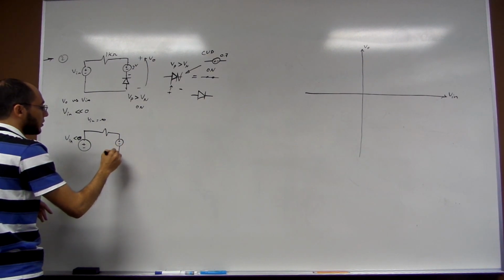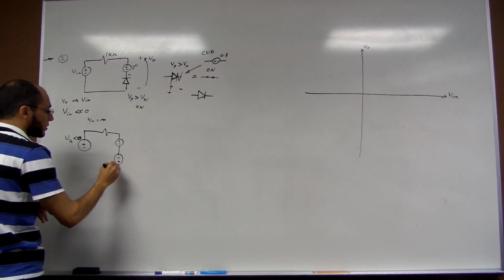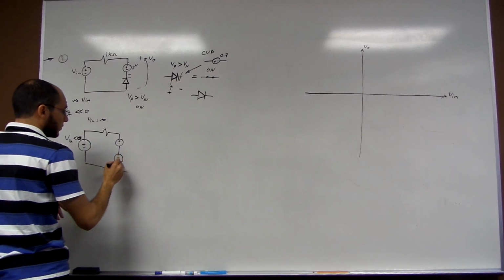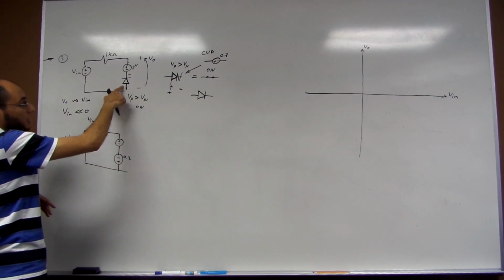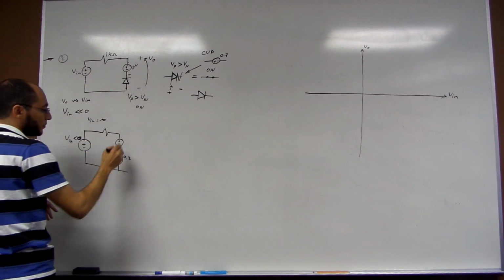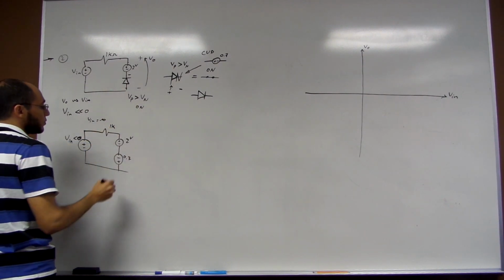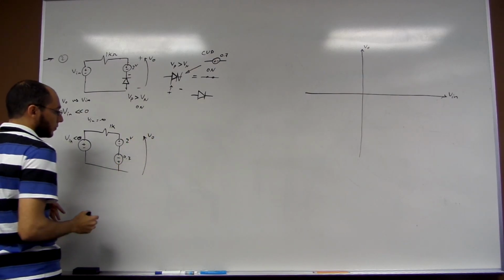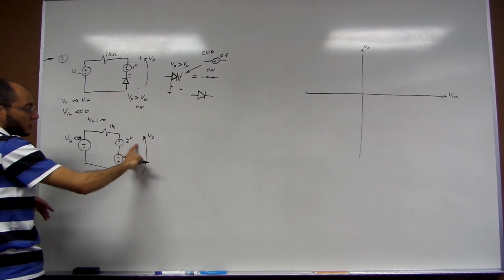Plus minus, and we have here a battery, minus plus. Okay, so that is 0.7. Why did I put the plus down? Because the plus should map with this triangle. Then 2 volts, 1 kilo ohms. And the required is this V output. Obviously, this output voltage is constant, it doesn't change, there is no resistor here, so the output voltage is constant.